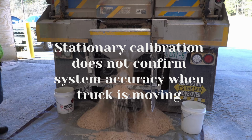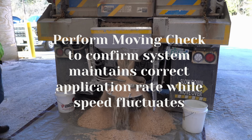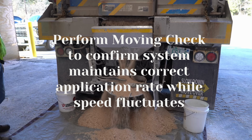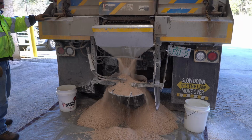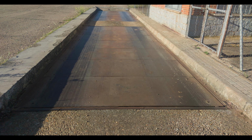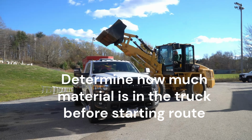Ground speed controlled systems continuously adjust output as a vehicle's speed changes. Therefore, the moving check will verify whether the system is maintaining the correct application rate while the truck is in motion. There are several ways to complete a moving check, ranging from highly accurate weighing methods to more practical field estimates. If your agency has access to a loader scale or vehicle scale, one of the most accurate methods is in-storm testing using actual material weight.